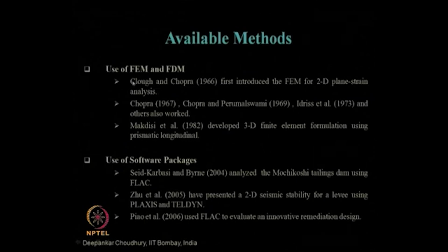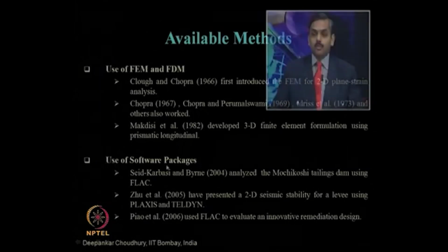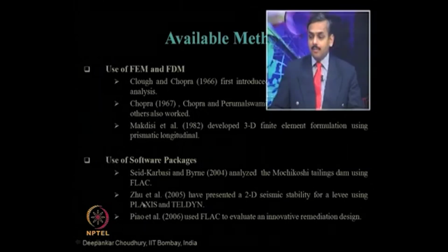Other methods are the finite element method or finite difference method. Clough and Chopra in 1966 first introduced the finite element method for two dimensional plane strain analysis for dams, and later on other researchers followed, the latest one being Magdisi et al. In 1982 they developed a three dimensional finite element formulation for this earthen dam.